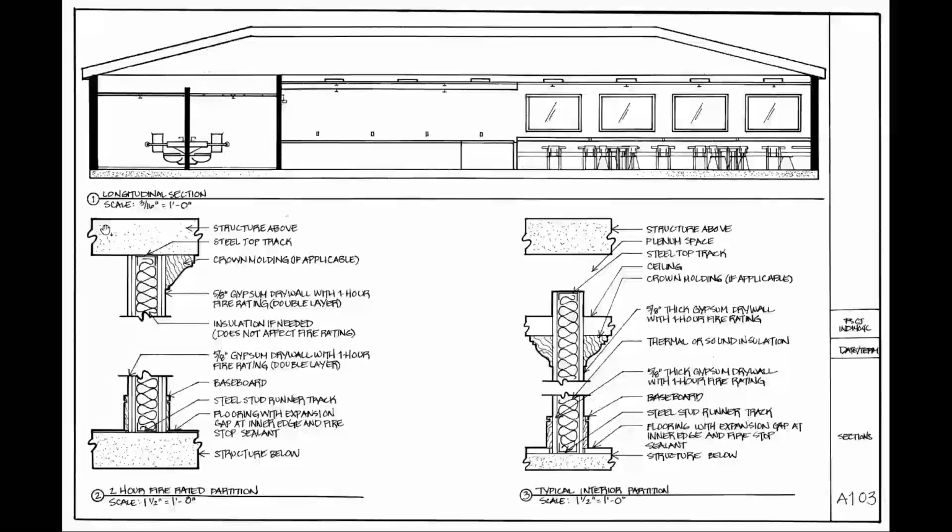So this break line here and here, they're just like a little S that cuts off the end. And what this break line means is this continues in this direction and it continues in this direction, but we don't want to show it all. So this structure right here is this right here. And we're basically saying, yeah, it goes all the way in this direction and all the way in this direction, but we're going to stop it right here because we don't need to repeat information.